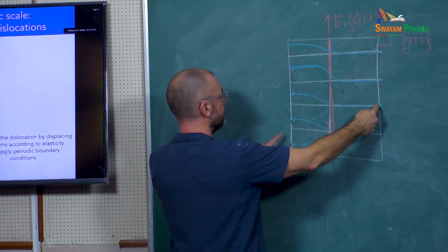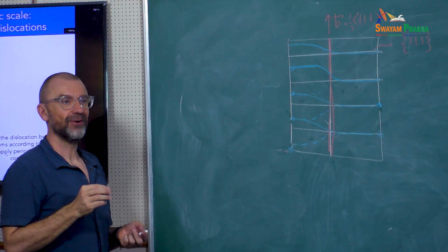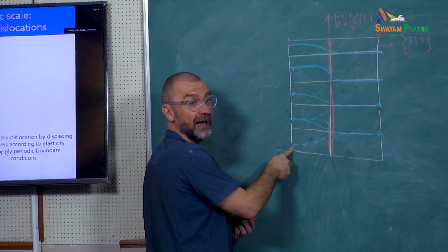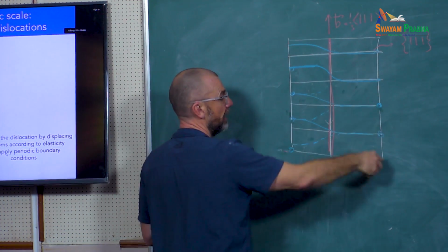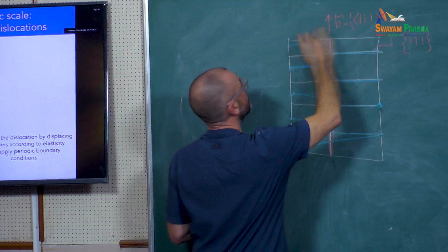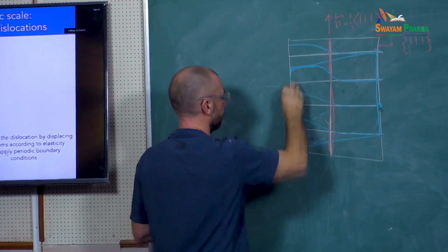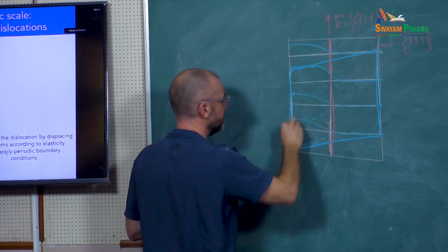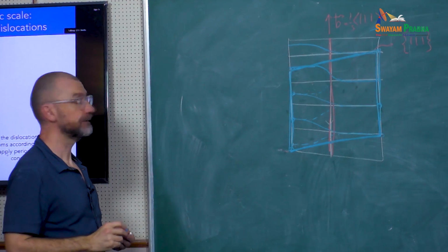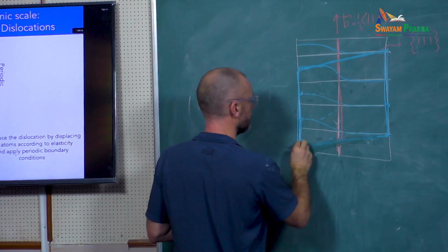Now here, I need to connect here to here. So what does it mean for the periodic boundary conditions? Or what does it mean for the simulation cell with this type of boundary condition? If the periodicity is from here to here, actually the simulation cell is no longer orthorhombic. It has a tilt. Or I would need one more atom here. No, it's here. If I define a simulation cell like so, sorry, this one should be at the middle here. Yeah, it's at the middle here.